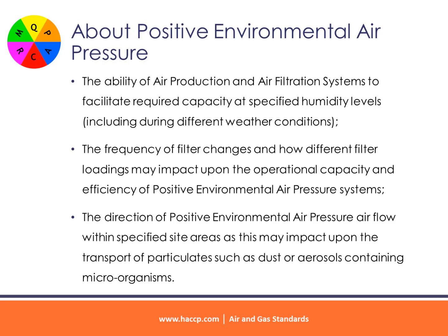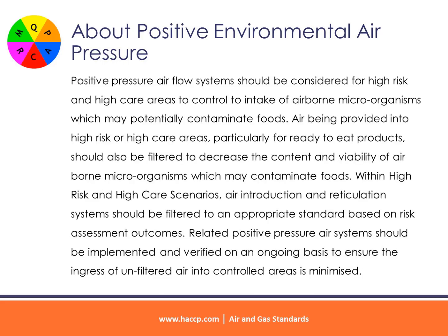The direction of positive environmental air pressure airflow within specified site areas, as this may impact upon the transport of particulates such as dust or aerosols containing microorganisms. Positive pressure airflow systems should be considered for high-risk and high-care areas to control the intake of airborne microorganisms which may potentially contaminate foods. Air being provided into high-risk or high-care areas, particularly for ready-to-eat products, should also be filtered to decrease the content and viability of airborne microorganisms which may contaminate foods.